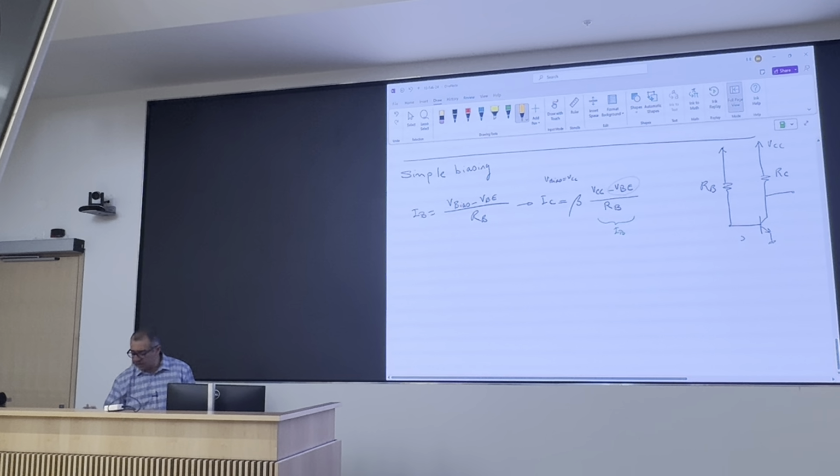That's not going to change much. Especially if I'm using the same transistor, a million of them will have, I don't know, a 50 millivolt variation in VBE. So VBE I'm not really worried too much about. RB, I can buy 5%, 2% resistors very cheap, and so RB again is not a big source of concern.